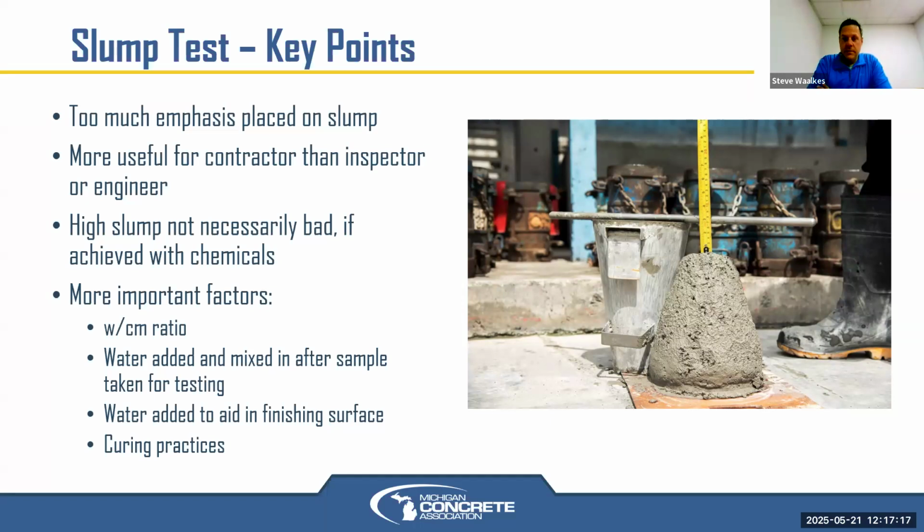We just had what was available, pretty much regular Portland cement, local aggregates, whether crushed stone or gravel, and local sand. The only quality control to check one batch versus the next, to figure out how much water we actually added, if everything was done by hand or by estimate as far as proportioning and mixing, was to measure the slump from batch to batch. And so that made sense.